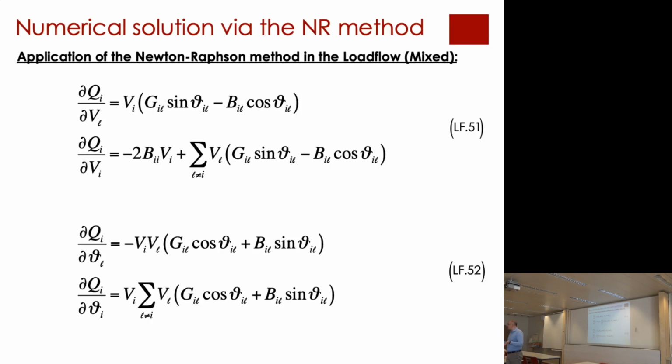Now, in your career, you will not write a load flow code. There are a bunch of software packages that solve the load flow problem for you, but you need to know how an engine that solves a load flow problem works. Because when you will be sitting in the control room of SwissGrid, you have to know why it converges, why it does not converge, which are the quantities to fix, which are the tolerances to fix. That's why you need to know how to write the load flow problem to use a given software package.